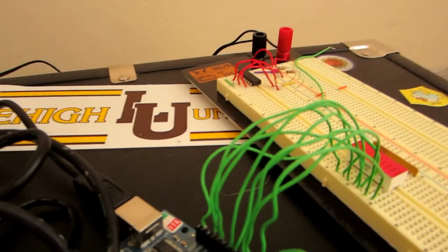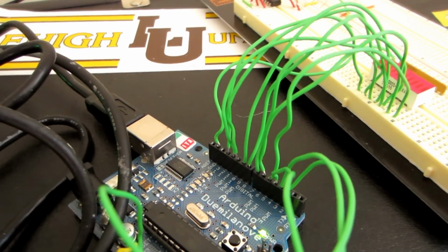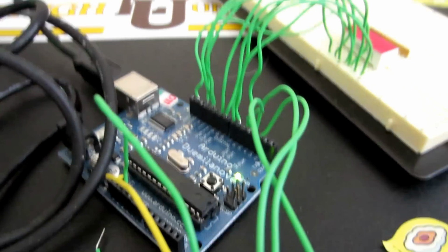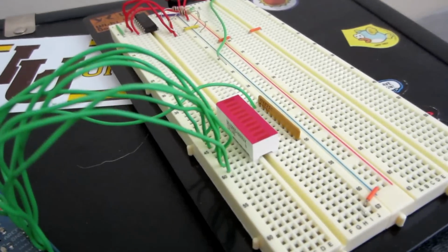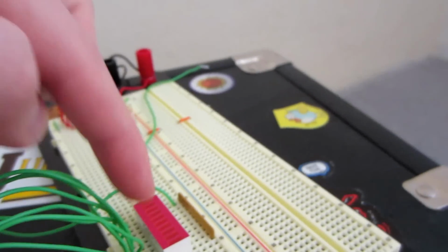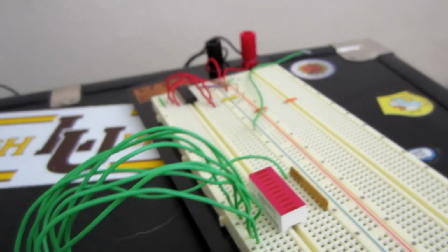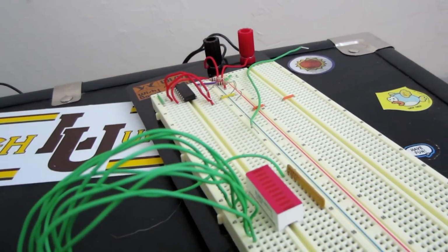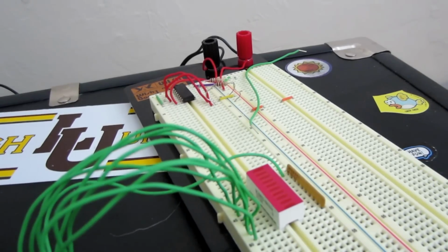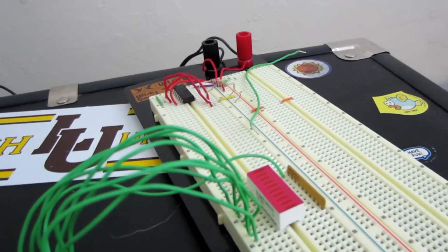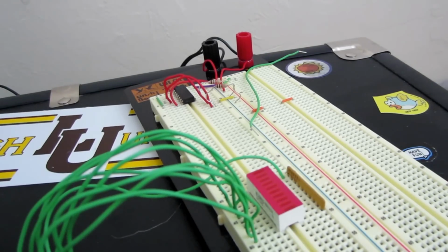Okay. Another thing I want to show you, so that's the serial communication. I also wanted to show you, I have some more pins coming out of the microcontroller, and those are output pins. And I'm using those to go to the solderless breadboard, and they were hooked up to an LED bank. And the reason why I did this was to show that you could also control other things than just serial communication, but you could actually control a motor or a light.